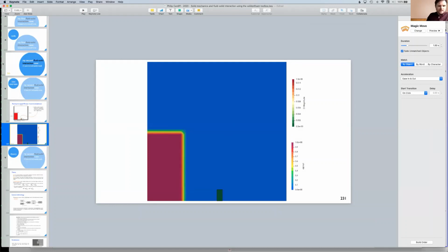I'm curious if it's possible to simulate the movement of an elastic body and a rigid body simultaneously, and how to choose. That's a good question. Not that the other questions aren't good questions, they're all good, but it's one that I have to think about. A brute force way to do it would be to set the stiffness of your rigid body to a very large number, and in effect it will become a rigid body, but that isn't maybe computationally efficient.